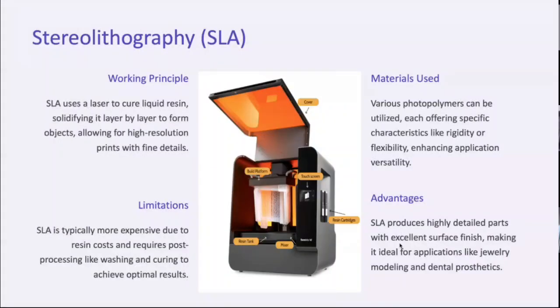Someone is asking if SLA is only used for small parts or particular 3D modeling. Not in that way. Compared to FDM, SLA is a little expensive and a little time-consuming. Basically, SLA can be used for things which require high precision, high surface finish and high geometrical similarity.